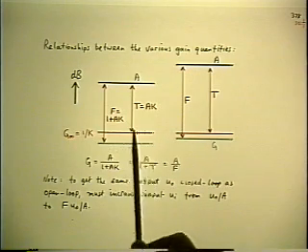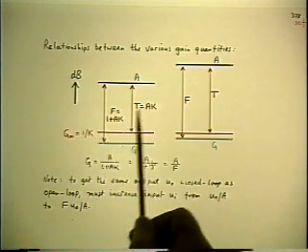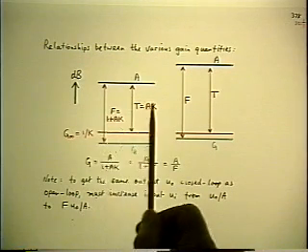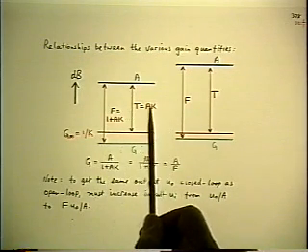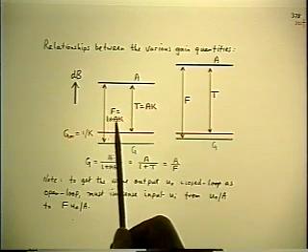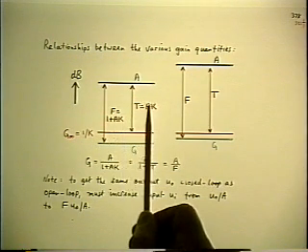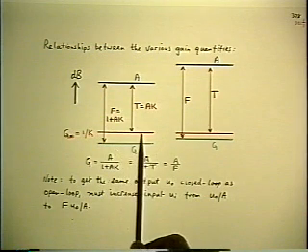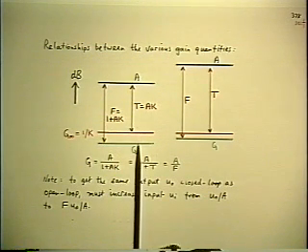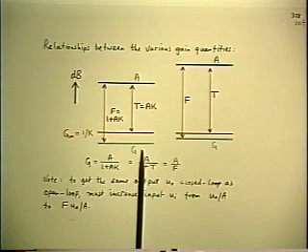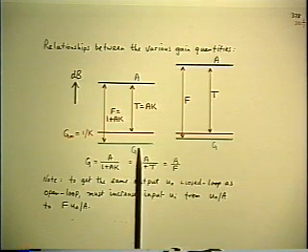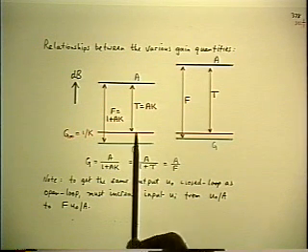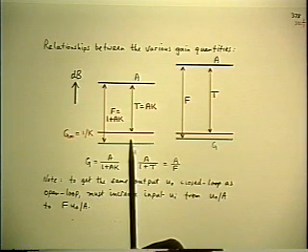And I'm glad you got that, because the tendency is to say the difference is 1 by looking at these other two quantities. But of course that's not correct, because the 1 is an additive term to the T, not a multiplier. So the difference between the red and the green line in dB is the discrepancy factor D, and as D approaches 1, the green line approaches the red line, because dB goes to 0 as the ratio goes to 1.